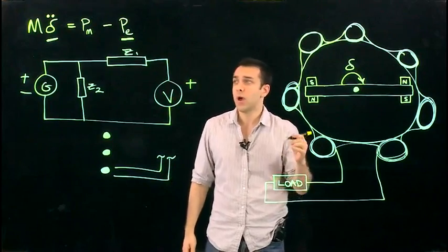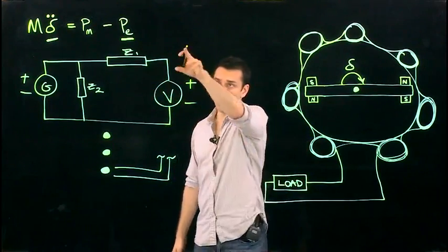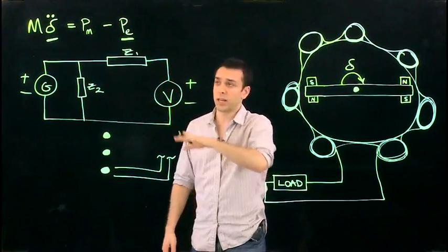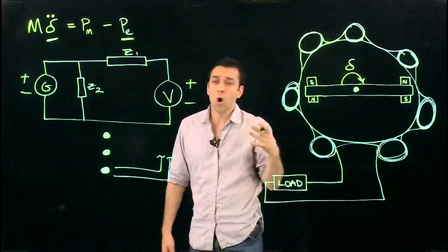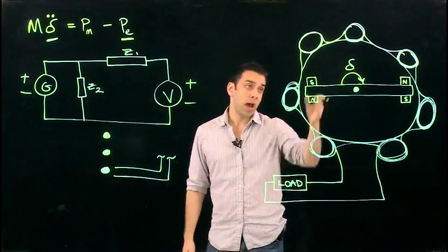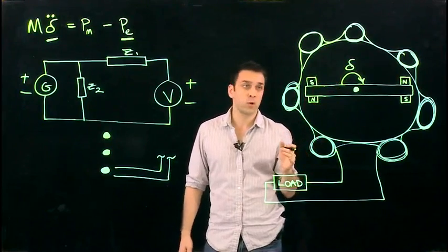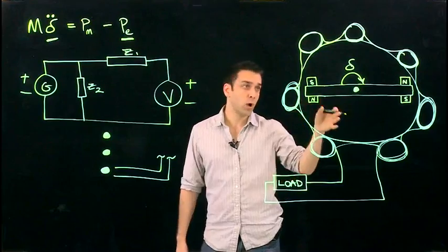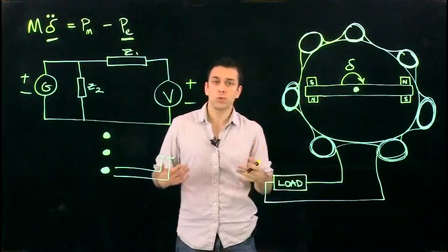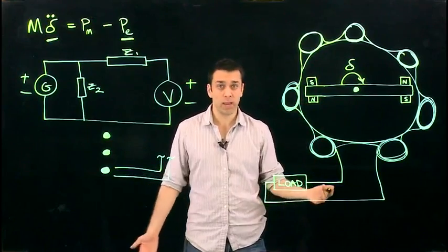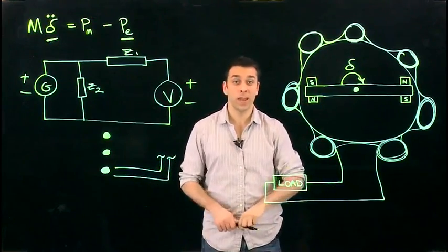So now we can compute the voltages at each of the different nodes at any point in the power grid. We can calculate currents, we can calculate power. We can also look at how different changing loads could affect and stress the generators and can result in different accelerations on different generator rotors. And so using these tools, we can now model how the grid as a whole will respond to things like blackouts, which is what you'll be hearing about next.